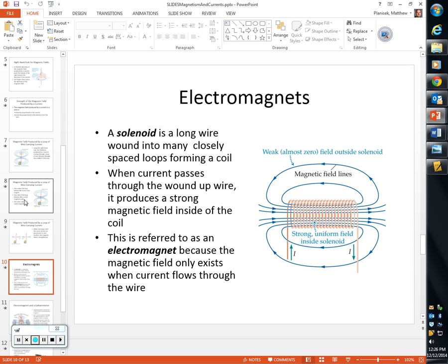That solenoid is a coil of wire that is wrapped into many loops. The more loops that you wrap it into, the more magnetic fields can be produced. But only if what? As long as there's current. If there's no current flowing through this wire, it doesn't do anything, right? That's why it's referred to as an electromagnet. Because unless there is current, unless there are electric charges flowing through it, it does not create a magnetic field. Good there? Okay. Let's transition to today's outline.